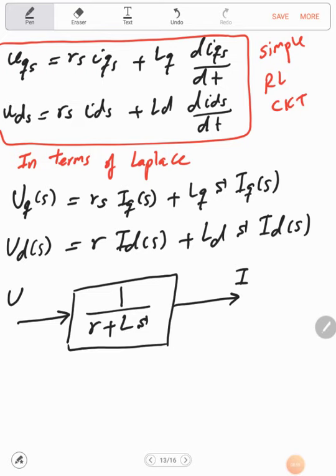So now we can design a current controller using our knowledge. This will be the I reference, and here I will put small i, and the small i can be either the Q-axis current or the D-axis current, which means that I'm plotting one plot to represent the two controllers.